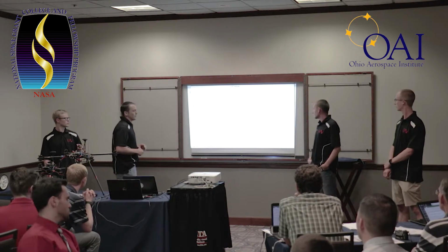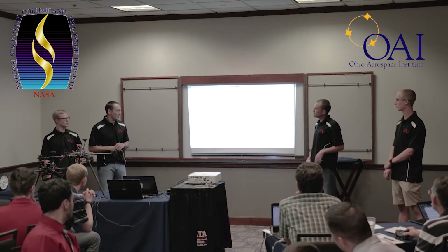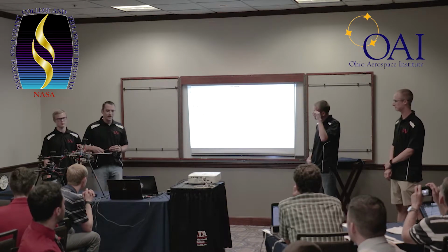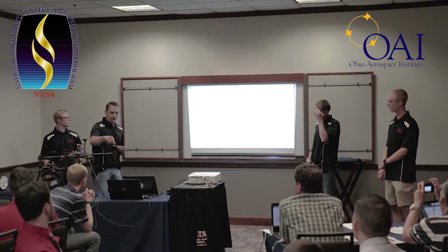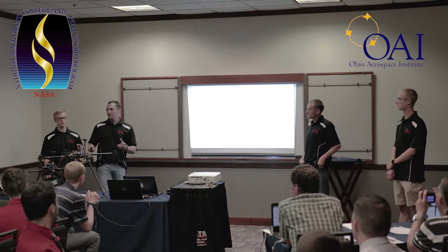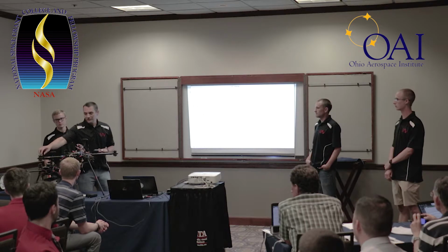Ran on 6S, 20 amp hour battery, would hover and fly for around 30 minutes or so of competition flight time. What happened during testing is we actually ended up having a bad batch of motors. So what you'll notice is that this motor and this motor are the same. That happened through testing. So we actually had almost a fire on the front corner motor here.